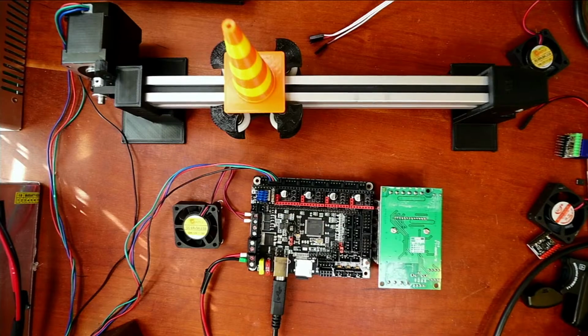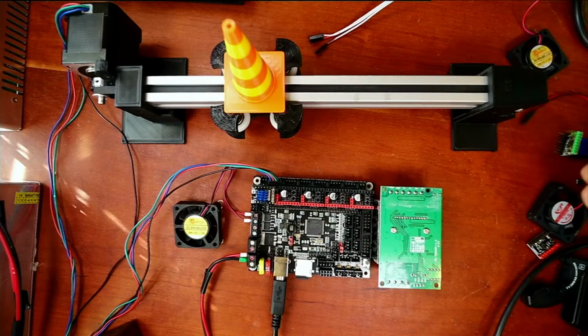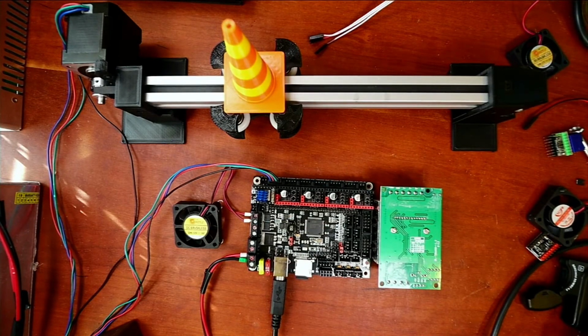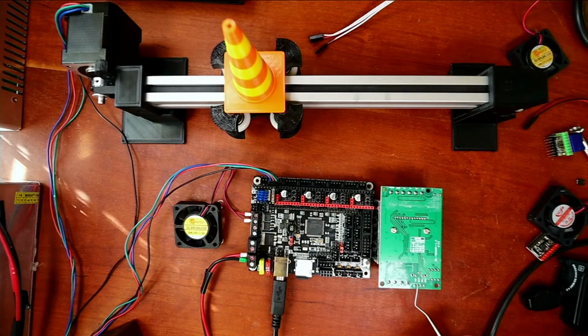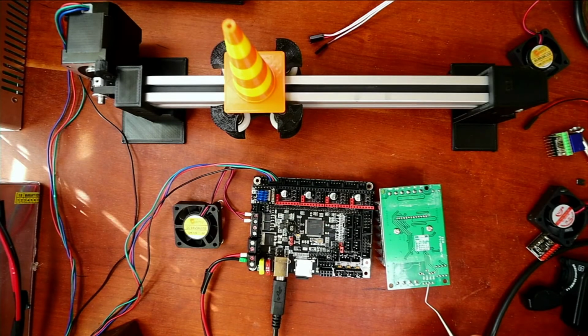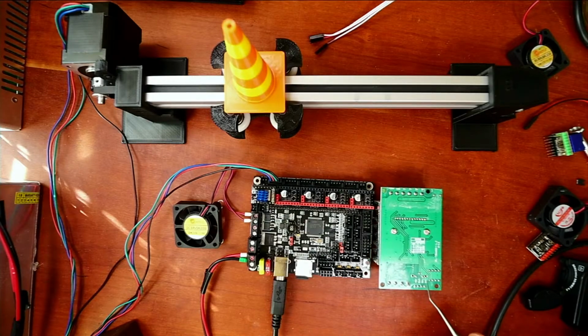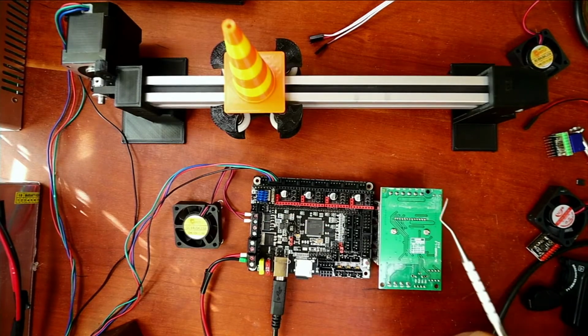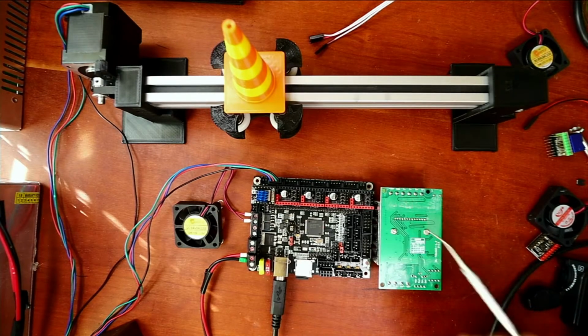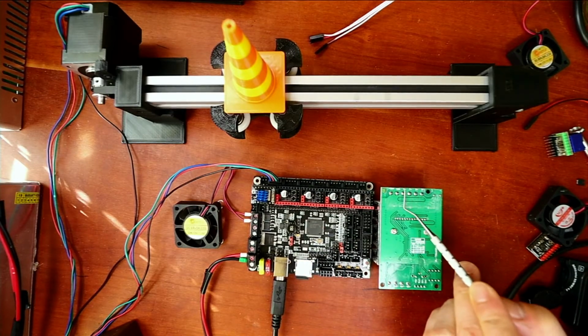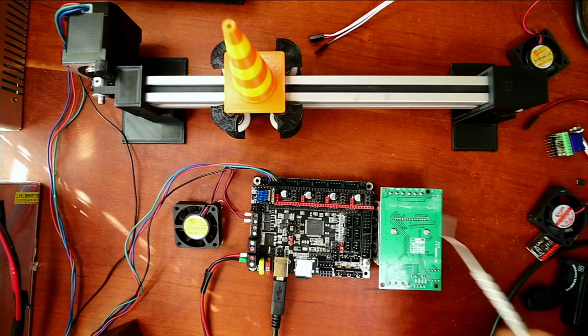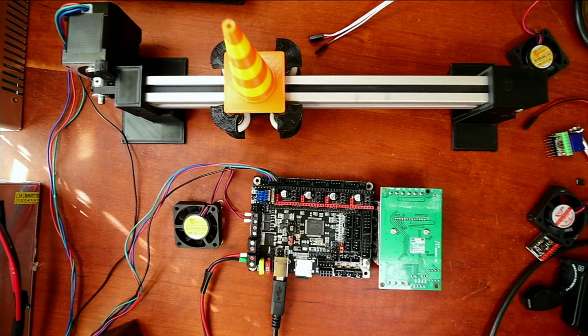So there's the back end of it. It's got some interesting writing on it. It says, let me pull out a little pointer here. It says 5 volts. Then it says CLK, which I'm assuming is clock. Then it says CW, which I'm not sure of, and then enable. So EN. So I'm assuming that's enable. Then over here it's got the pins that possibly match up to right here for your pins. So it's got an A+, A-, B+, B-. And then it looks like it takes upwards of 32 volts.